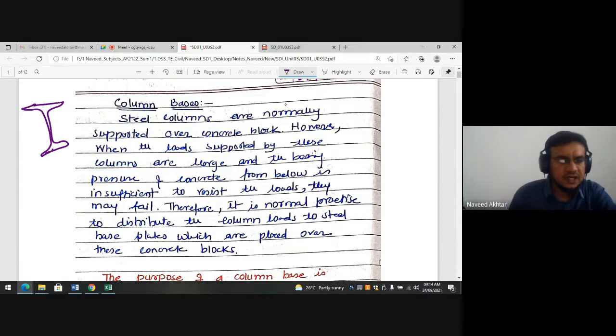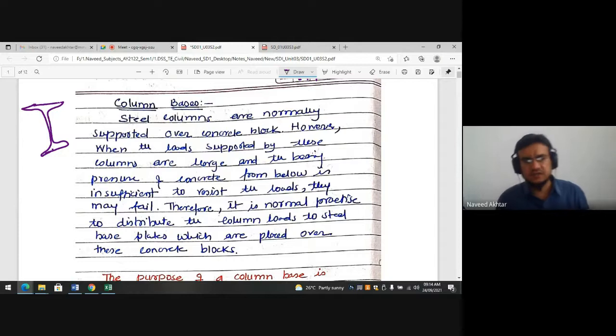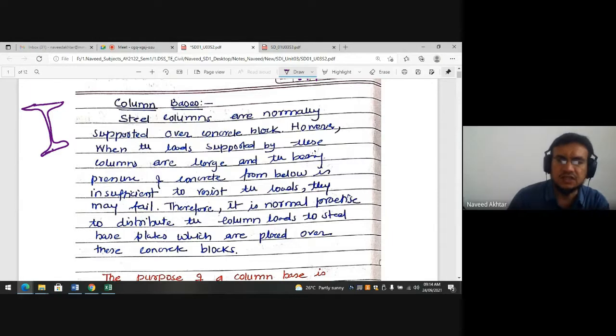But the bearing capacity, because all the columns are rested on the concrete, because steel we cannot use as a foundation due to its disadvantage that it corrodes, or it attacks with the sulfate and then carbonation takes place, and that will corrode the steel, and the strength of the steel will be lost after a few years. The sectional dimension may be reduced due to this corrosion effect.